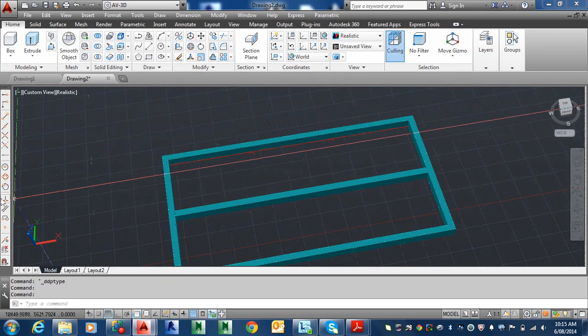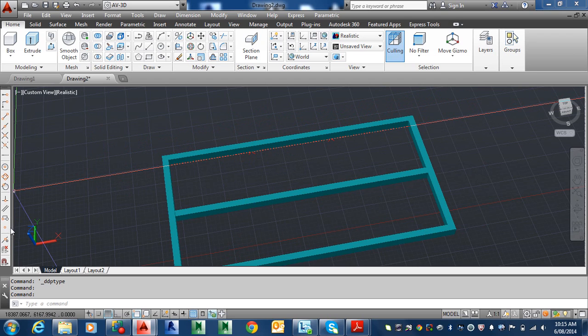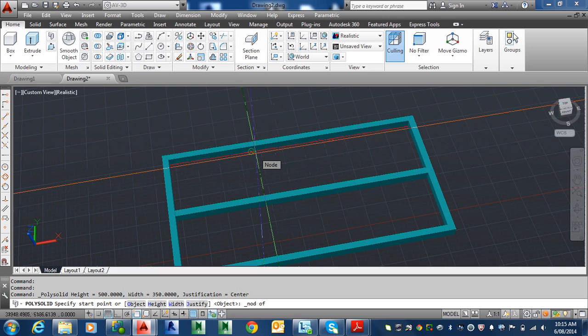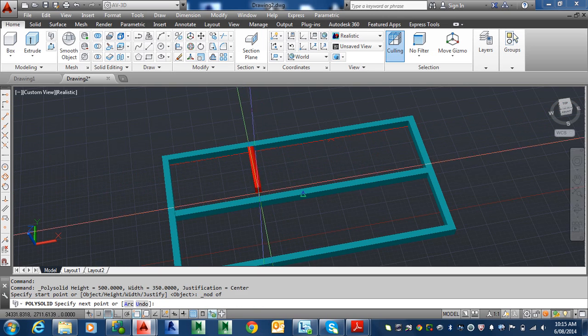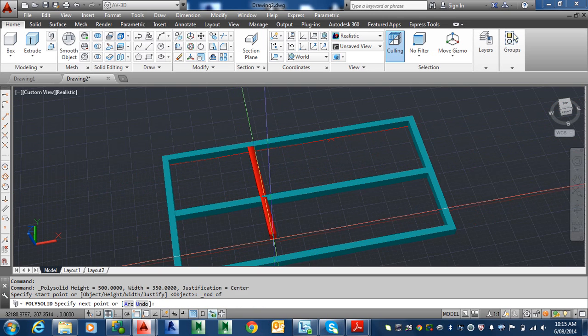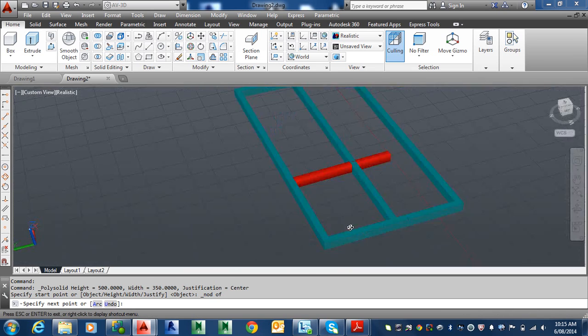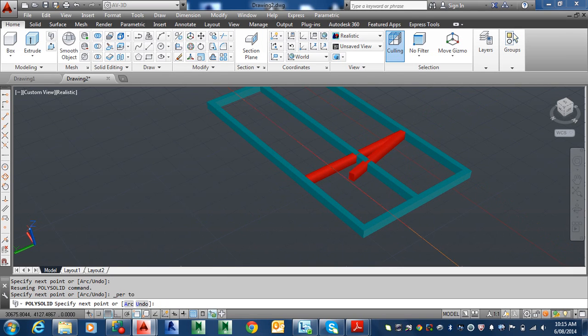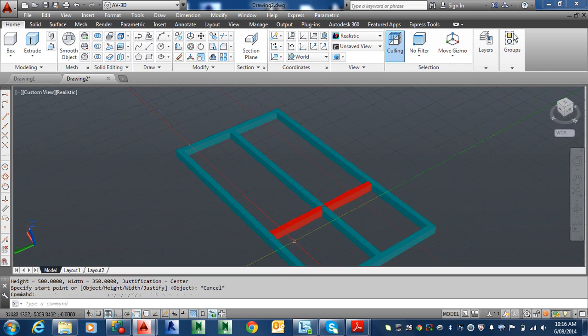Now the thing with that, when you need to use the node to latch onto it, so I will just pick it when I need it. So let's go with that. Click the node and go here, and it should pop onto that. See that node? And then across here, sorry, I'm in the sketch layer, we'll fix it up later. And now we're going to cross the road, go perpendicular to this one here, and enter.